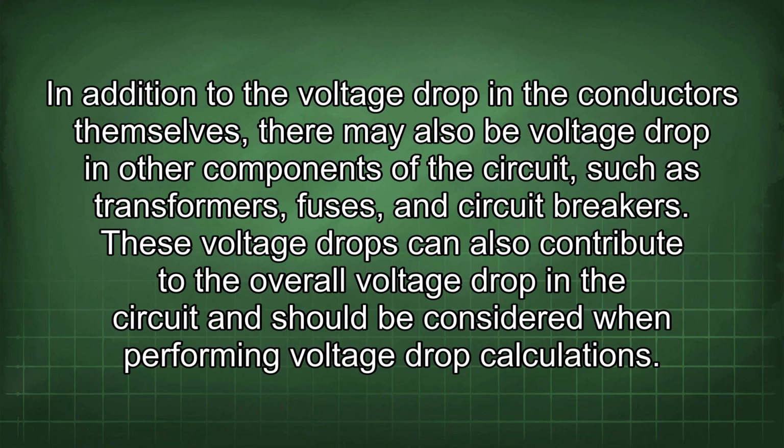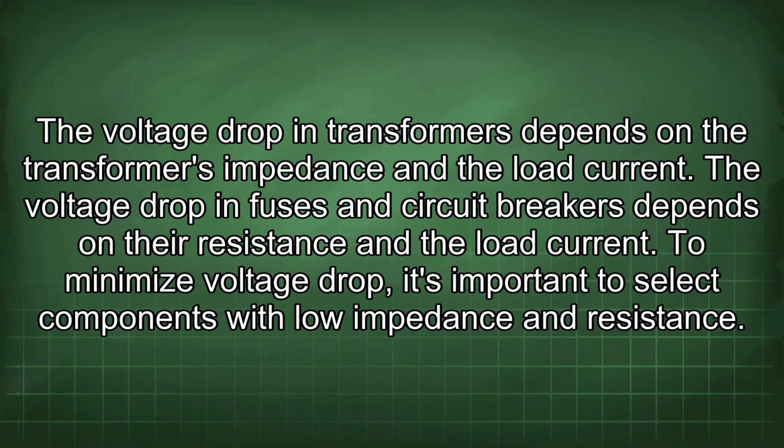In addition to the voltage drop in the conductors themselves, there may also be voltage drop in other components of the circuit, such as transformers, fuses, and circuit breakers. These voltage drops can also contribute to the overall voltage drop in the circuit and should be considered when performing voltage drop calculations. The voltage drop in transformers depends on the transformer's impedance and the load current. The voltage drop in fuses and circuit breakers depends on their resistance and the load current. To minimize voltage drop, it's important to select components with low impedance and resistance.